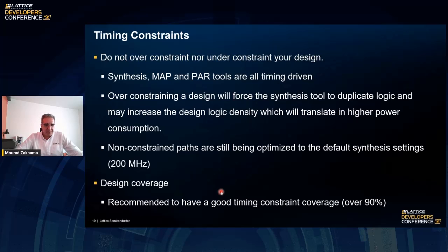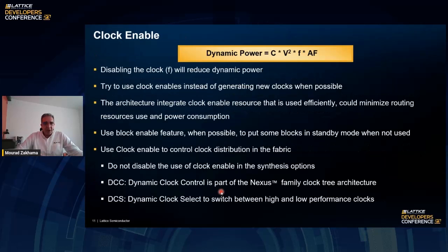Making sure that all your timing paths are covered will guarantee that there's minimal discrepancy between what you see in the functional simulation and the hardware behavior. A non-constrained path could create intermittent problems in hardware. So it's very important.